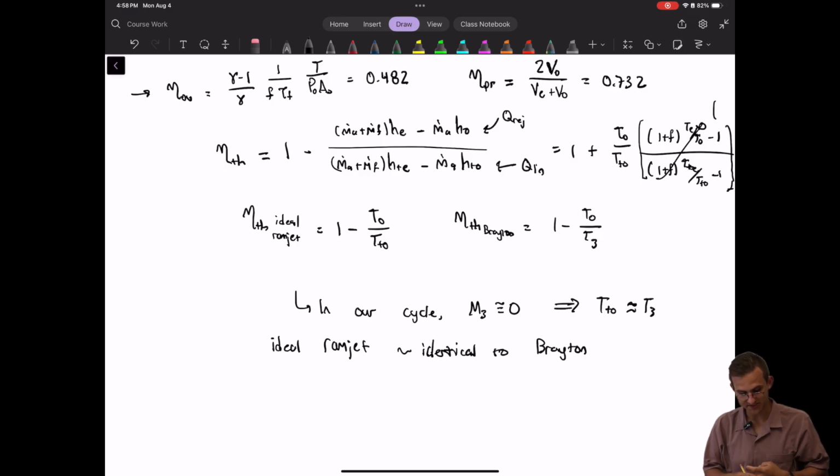But I will make a note here that this overall design is actually not very practical because the inlet is extremely sensitive to downstream conditions. Like if you slightly increase the heating, for example, you add more heat, or you decrease your overall speed, you can cause that unstart condition, which has a normal shock in front of the frontal region of the engine. So practical designs usually require some sort of inlet shock for stable operation.